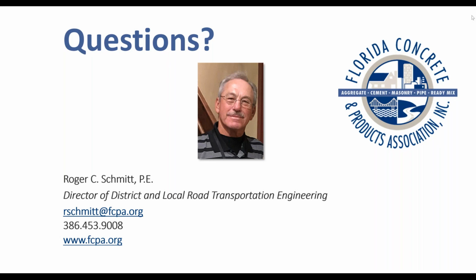I also believe in concrete tied shoulders, but the DOT has decided on the widened lane for edge support. So let me answer the question and say we've also seen some lanes being 13 feet. But I think the DOT has settled on, if they're going to do a widened lane, it's 14 feet. So let's say the minimum would be 2 feet. And that's kind of the same size as some of the curb and gutters you see too, that may be 2-3 feet wide. So I hope that answers your question.